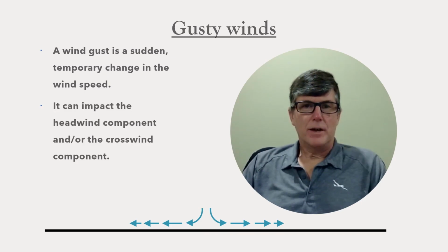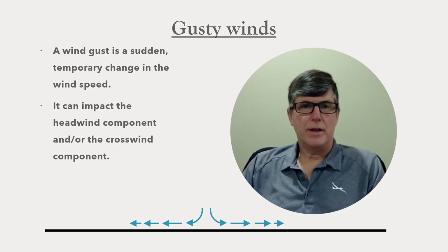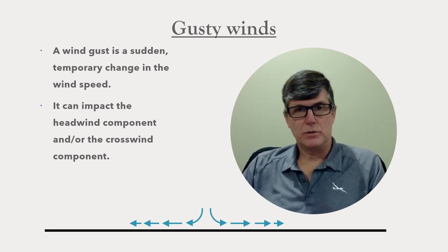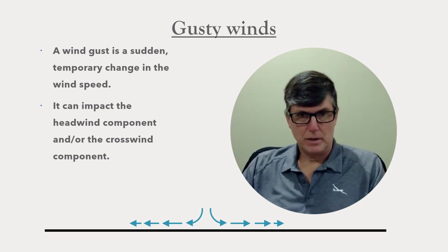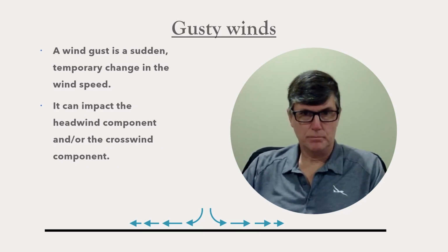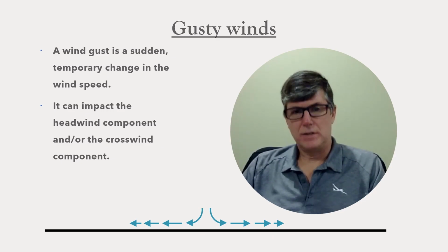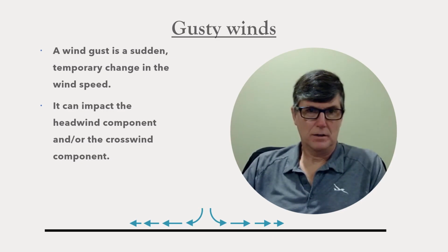If an airplane flies directly through the center of that vertical column, then it will experience an increasing headwind as it approaches the column, a rapid switch to a tailwind as it passes through the column, and then a gradual decrease in the tailwind as it flies away.